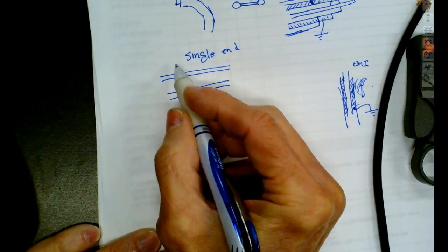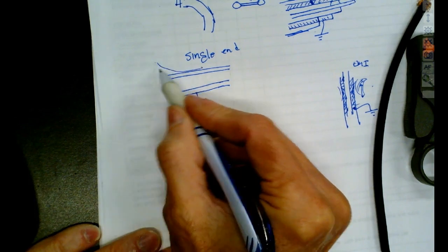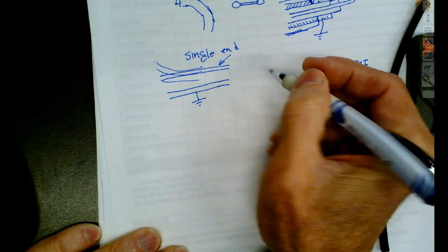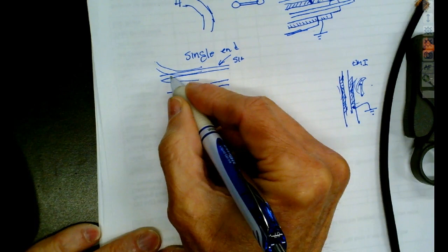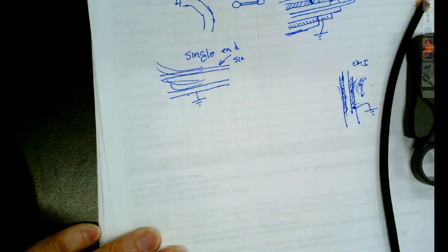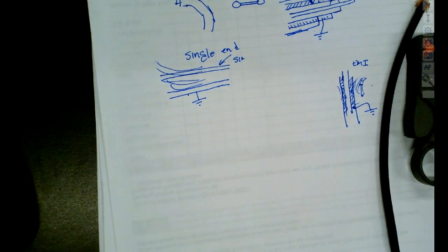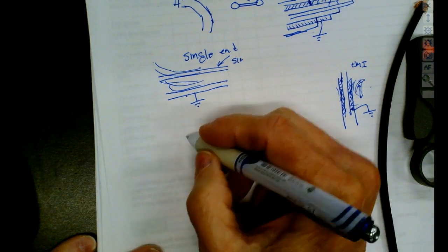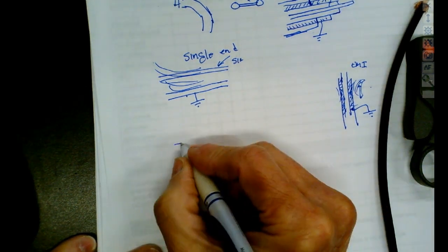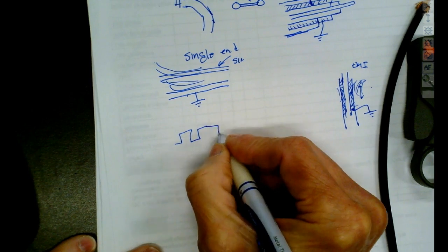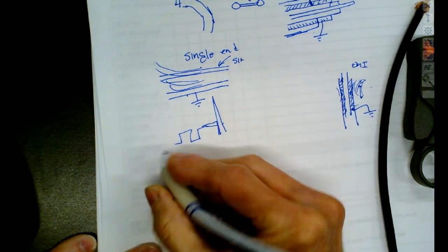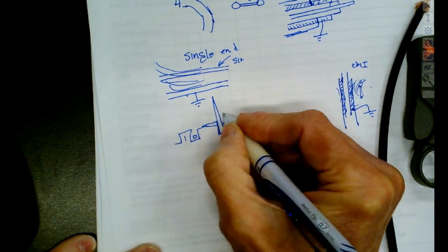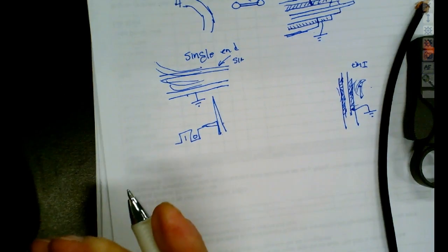But what was happening is when electromagnetic interference would come through the wire, it would induce into our signal lead, but it wouldn't induce into the ground lead, because a signal can induce a voltage into earth ground because that's what it's looking like. So what would happen is I'll be trying to send information, and this would really show up on digital. So I'm trying to send digital information, and we'd get a big old voltage spike in. And then, of course, if this was a digital 1 and this was a digital 0, I just screwed up because I put different packages in there.